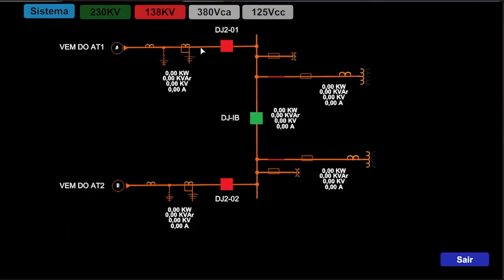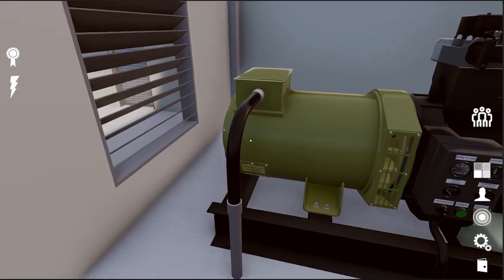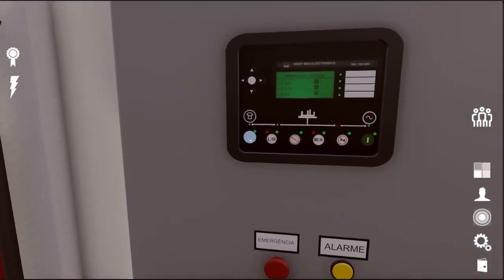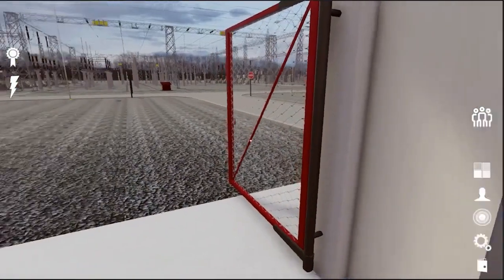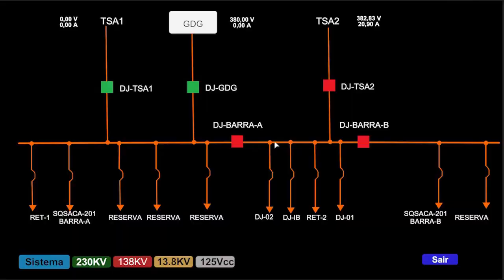At this moment, it has fallen significantly to 380 units. The automation system has already successfully toggled both of the circuit breakers. Now I'm going to shut down my diesel. And now I have current here in my auxiliary service. I've normalized the substation. So all of this, folks, was based on a simulation.